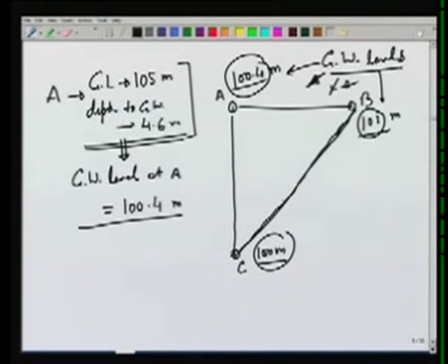So if we divide this into 5 parts, then this would roughly be 100.4, and that means the line joining A with this point will roughly be a line where the groundwater elevation is 100.4, and then we can draw lines parallel to this from all the points.